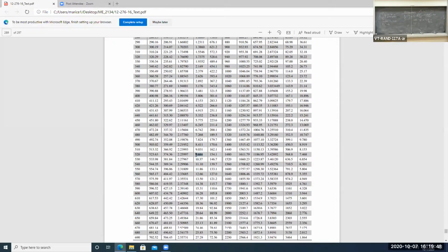So we're somewhere around 520 degrees, maybe 522. The exact value for temperature is 522.4 degrees once you do a little interpolation between these two data points. So T2 is 522 degrees, and this is interpolated from B11, okay?